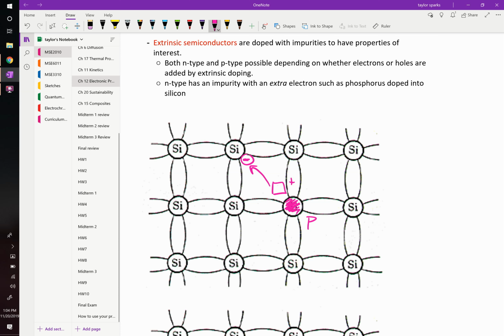We created a positive charge. Everybody with me? So in this case, the electron is vastly more mobile than the phosphorus atom. The phosphorus atom could diffuse, but it has to replace other atoms. That's going to be way slower. Diffusion of mass is way, way slower than the electron, which is occupying that top level of the double-decker bus. It can move around really easily.